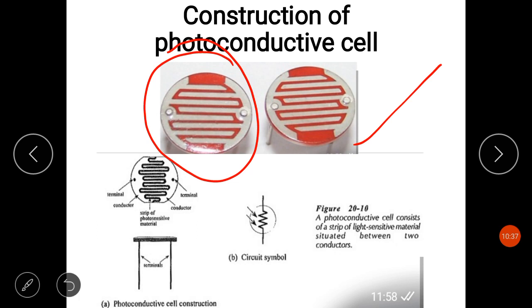So sintering is a heat treatment process in which a large quantity of loose material is subjected to sufficiently high temperature and pressure, where the temperature and pressure should not reach the material's melting point, but should be slightly less than it. That causes the loose material to become a compact solid piece. This is how the chemical sintering occurs.